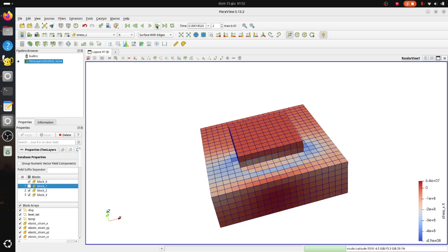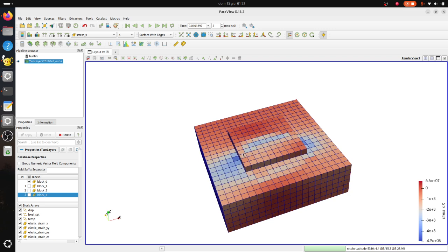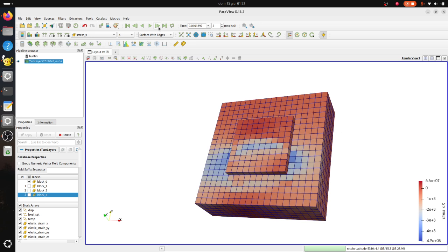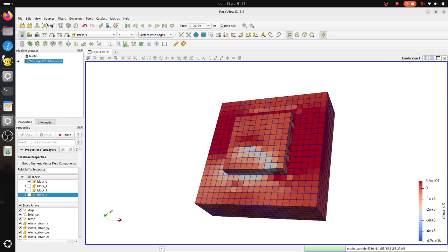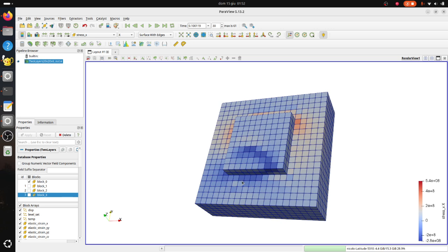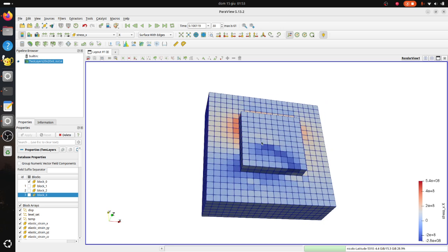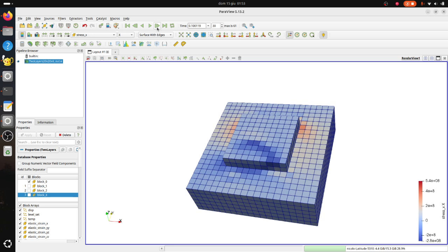And then when the next layer starts, so the next scan starts, you create compressive residual stress elsewhere. You can see the scan creates all the compressive residual stress. Okay, and this happens mostly during the scan, but then there is the cooling effect. You can see it induces this tensile residual stress here and here. So, and at the end you can assess the residual stress.